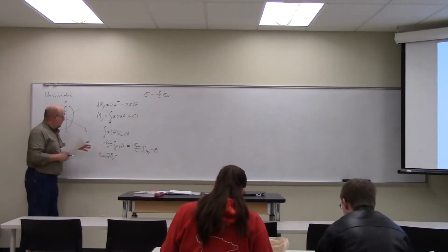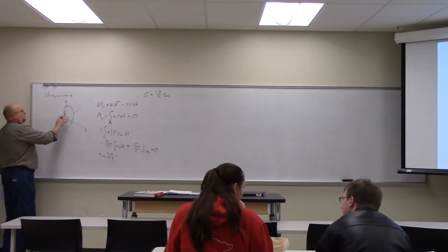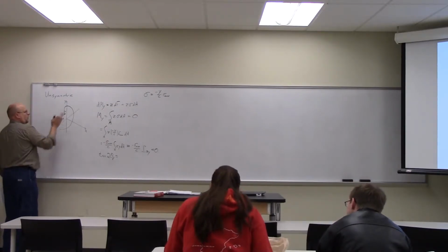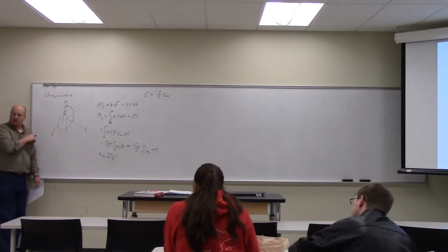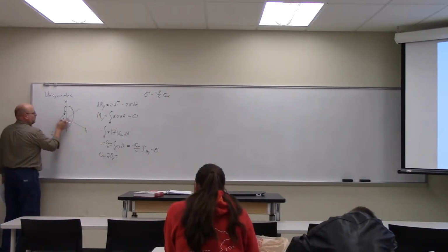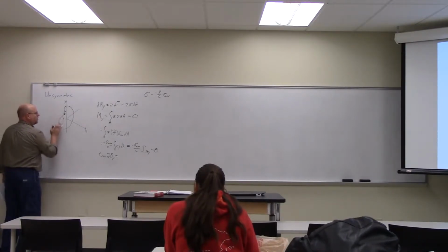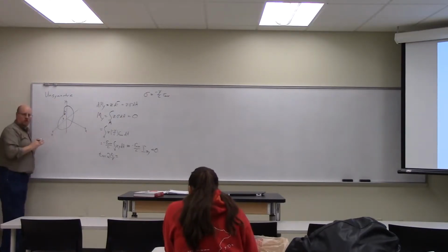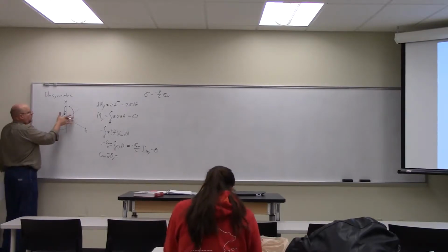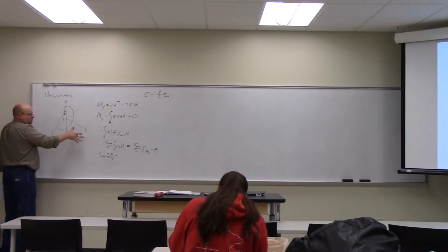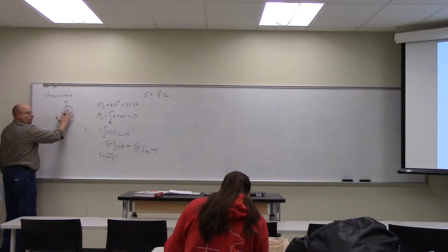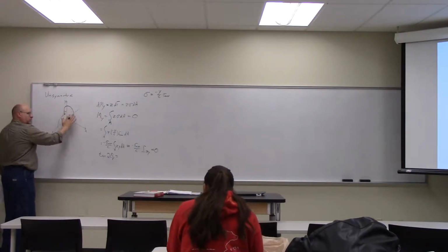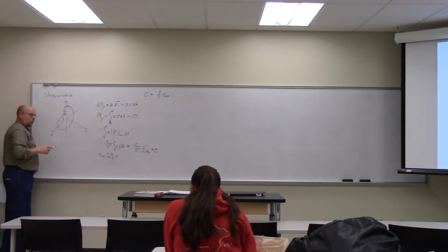Okay, so if we rotate, in other words, this thing wants to flip about this direction or that direction, if you will, using the phone analogy. It would most readily rotate about this direction or that direction because those are the minimum and maximum moments of inertia. So theta p was about figuring out what angle we needed to rotate our coordinate system to get to that minimum and maximum orientation.